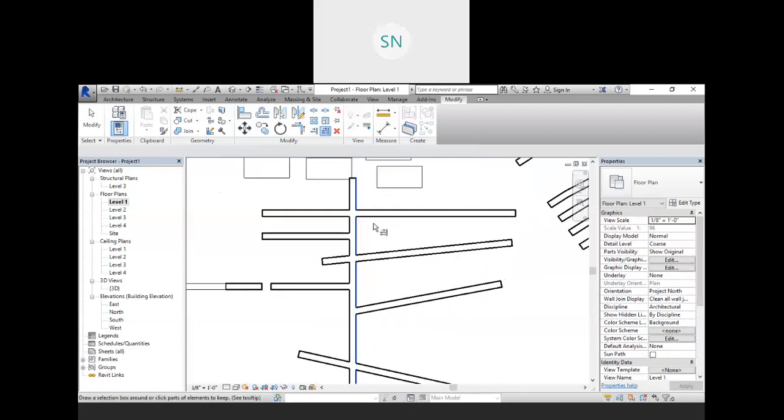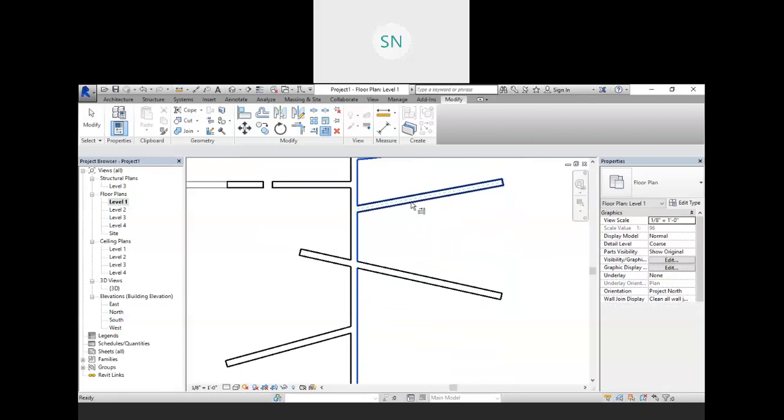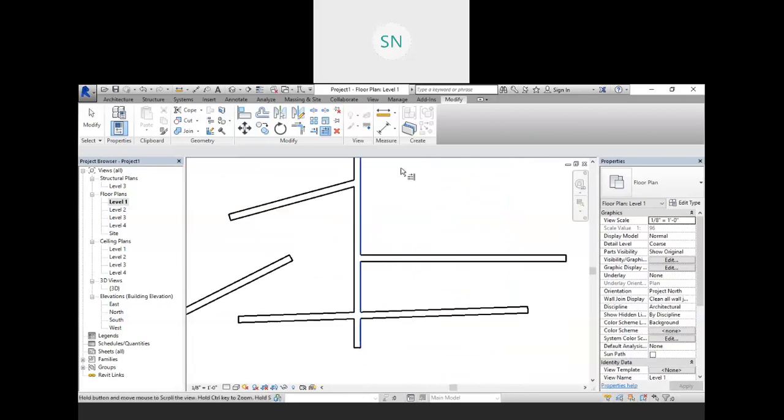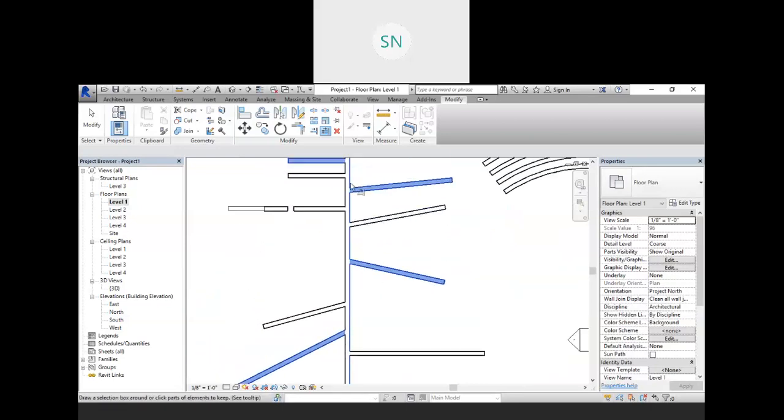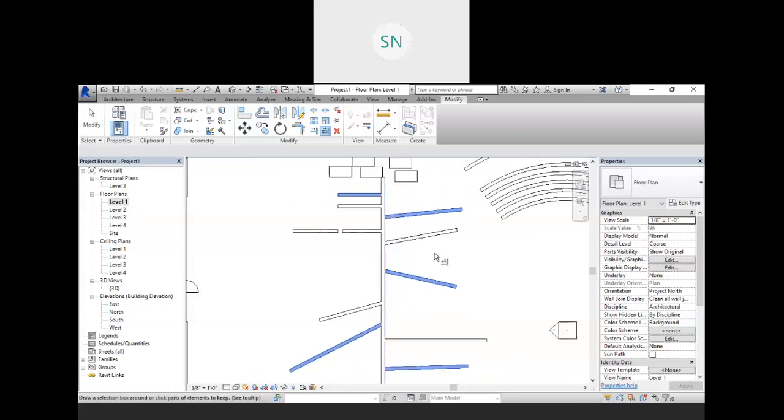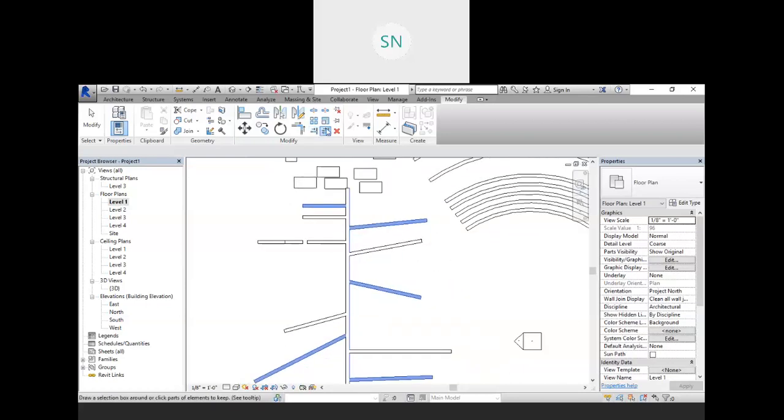Now select your objects only, that I want to keep this, this one, I want to extend this line, and I want to trim the opposite side. So you have to provide the target only a single time, right? So these are the options we have: trim and extend in single element and multi element.